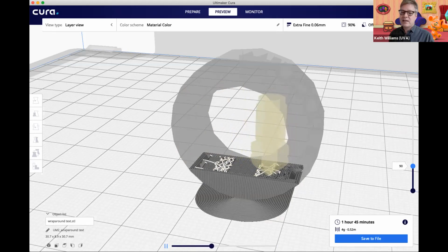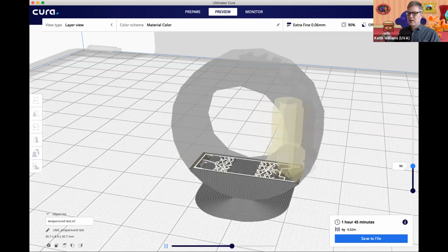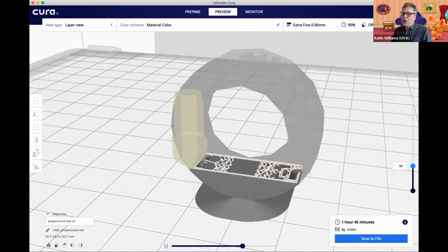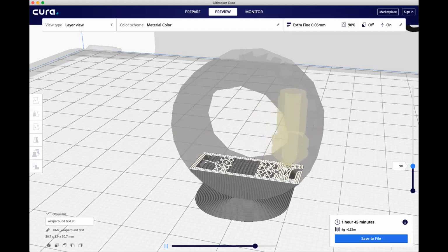You may see that there's a really weird fill pattern happening here. I actually selected gyroid fill. So that blue object that you passed around, I'm using that fill pattern for this ring. That's why it looks kind of zigzaggy. Look how quickly it writes along the XY plane. This is what we call the fast axis, or maybe we should call it fast axes or fast print plane. In the XY plane, the printer can move very, very quickly and it can spit out plastic really, really quickly.